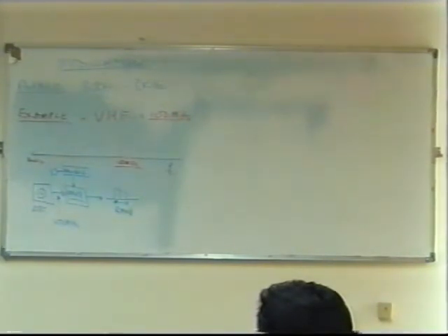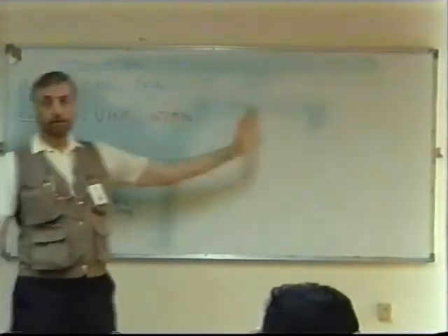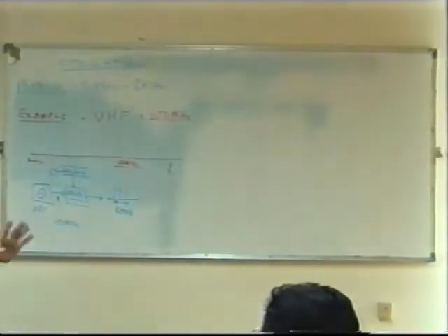The rate at which you transmit or convey information depends on bandwidth, doesn't it? If you reduce your bandwidth to 0, then you're not giving any information to anybody. So the wider the bandwidth, the more information we can give. We need a certain minimum bandwidth for our audio signal, in our example here, like for a telephone channel. And so therefore we need to produce a band of frequencies. This would then go through to an amplifier and an antenna and be sent to the receiver. I'll talk about the receiver in a minute.